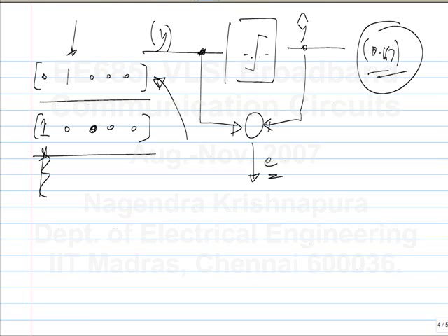No, if you restrict the coefficients, there is a distinction. If you see, in my definition, cursor is the maximum tap, okay? It doesn't have any special place other than the fact that it is the maximum value, that's all. Also I had given some restrictions on coefficients. I gave the largest range for this and smaller range for these things. So, in that case, it is legitimate to interpret this as the cursor and the rest as either precursor or post-cursor. But if you have unlimited range, yeah, that is another thing.